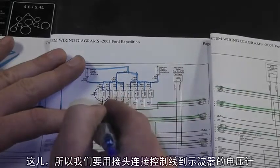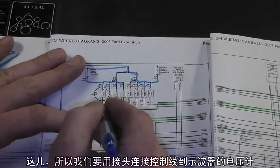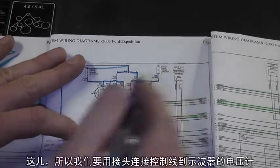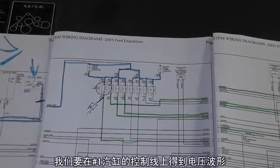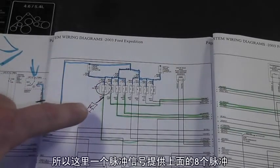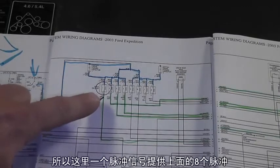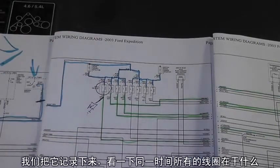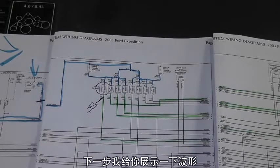So we're going to put a connector, back probe this control wire with the voltmeter part of our scope. We're going to do a voltage waveform on that number 1 cylinder control wire, and so what we'll have is 1 pulse on this signal for every 8 pulses up here, and we'll be able to coordinate them together and take a look at what all of our coils are doing at the same time. So we'll take you up to the board next and show you the waveform.